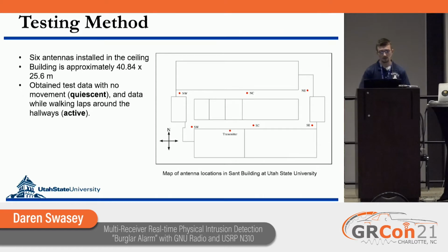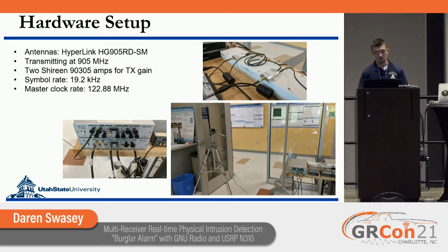And this is what the data looked like from the PLL on this next slide. Getting ahead of myself. So here's the hardware we have. We have 2 USRP N310s. I'll try to use my mouse there so people online can see too. The first is connected to the transmitter, which comes over here, gets fed through these 2 amplifiers that each amplify at 12 dB.